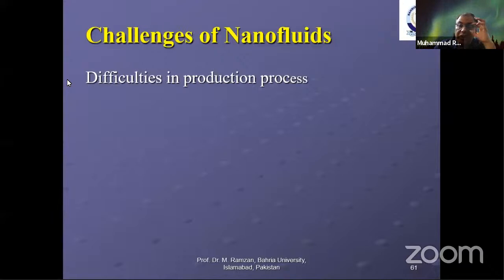The manufacturing of the nanofluids has employed either a single step, as I told you here, that simultaneously makes and disperses the nanoparticles in the base fluids, or the two-step approach that involves generating the nanoparticles and subsequently dispersing them. Using either of these two approaches, nanoparticles inherently are produced from processes that involve reduction, reactions, or ion exchange. Furthermore, the base fluids contain other ions and reaction products that are difficult or impossible to separate from the fluids. Another difficulty encountered in nanofluid manufacturing is the nanoparticle tendency to agglomerate into larger particles, which limits the benefits of the high surface area.